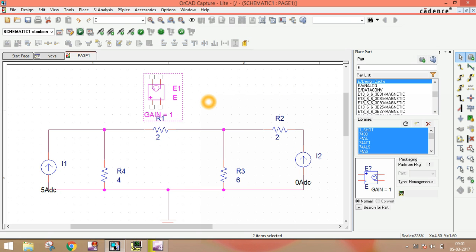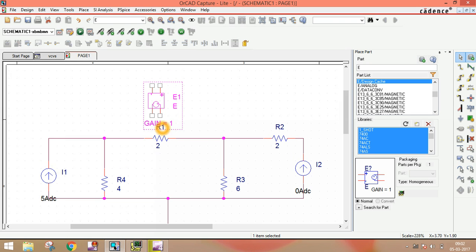Some rotation problem, so if you rotate, you have to connect like that, because the positive terminal is here, so positive, the circuit is here, and negative here. I forgot that our circuit has 2Vx. I did not change the gain. If it is 2Vx, the voltage of this is twice the voltage of that, so you have to set gain 2. If 3Vx, then 3.